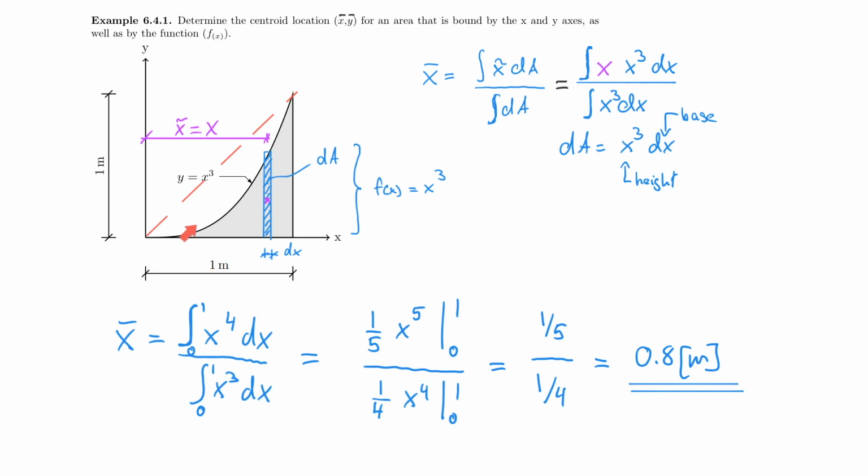And now in this case, I'm actually carving out a component. That means the material gets heavier on the right side relative to where it was when it was a triangle. And therefore it needs to be larger than 0.66, which is the case. Also, it cannot be larger than 1, and that is also the case. So I solved this. That's fairly straightforward. So I solved for x bar.